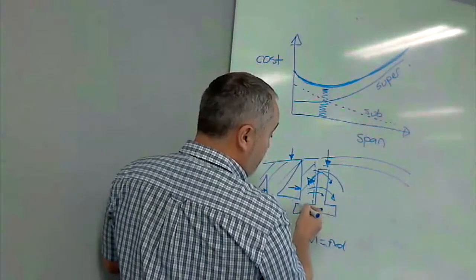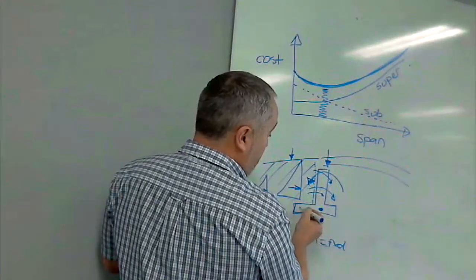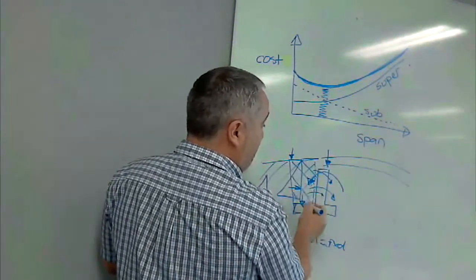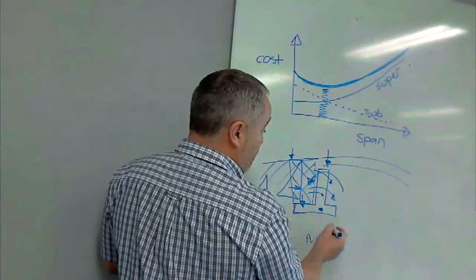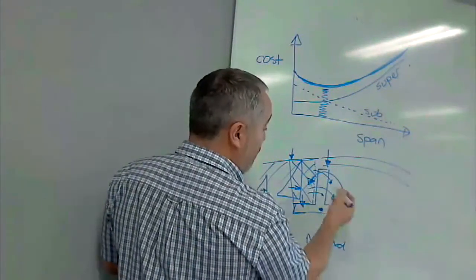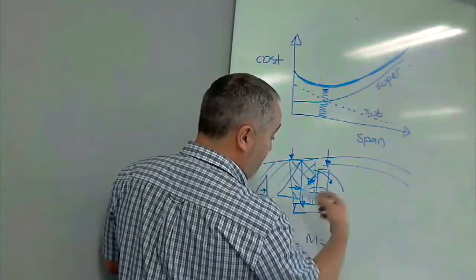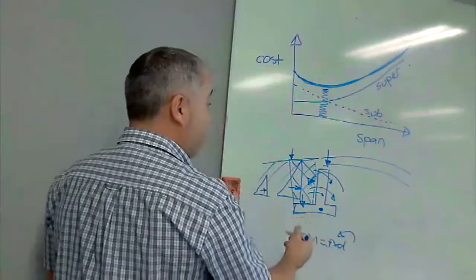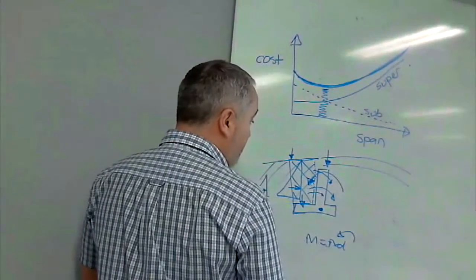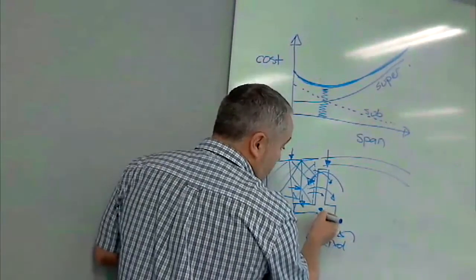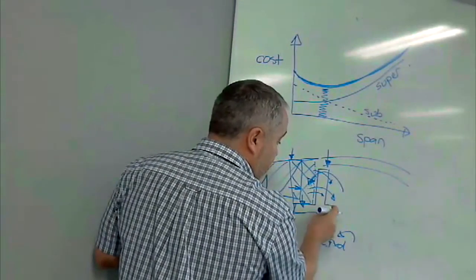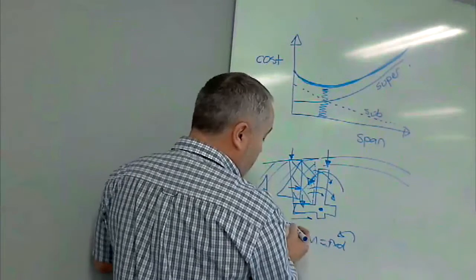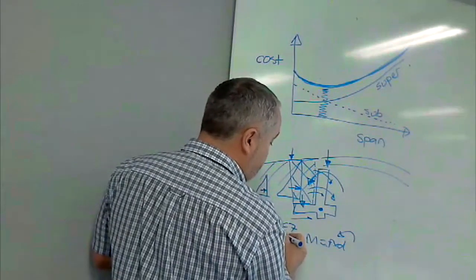You've got the weight of the concrete, so that would be the force coming down, and also you've got the weight of the material that's holding it down. So when you come to design something like that for overturning, it's just a matter of looking at all the forces clockwise, and you should make sure that the anti-clockwise ones are just a little bit more, so the whole thing's not going to tip over. You might find that you could have an extension down there if sliding is a problem. But you analyse all of this by Eurocode 7, which is the geotechnics.